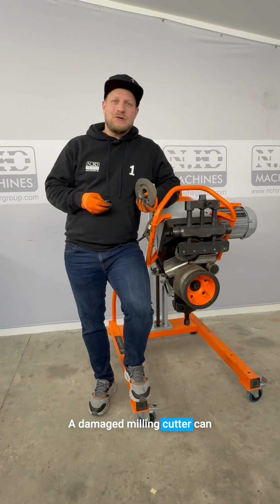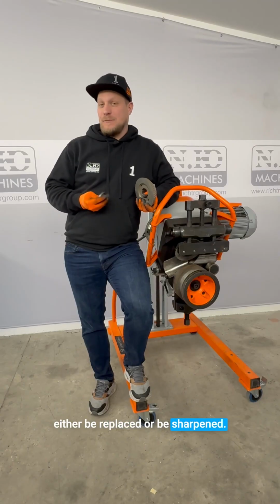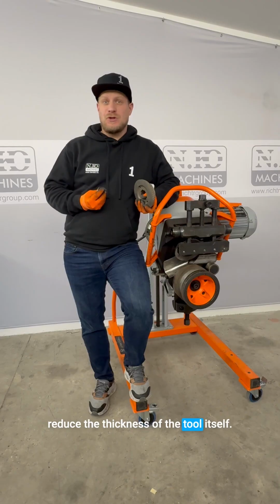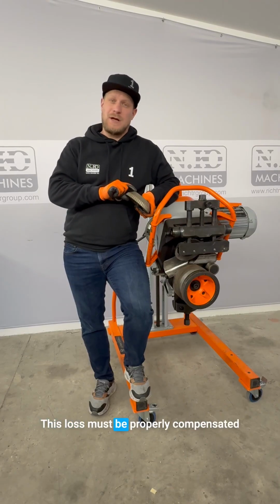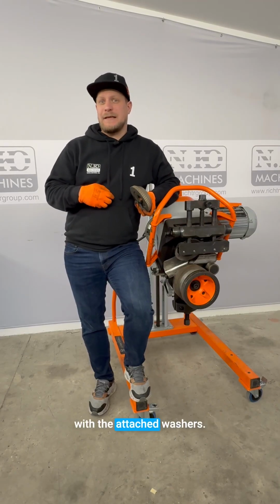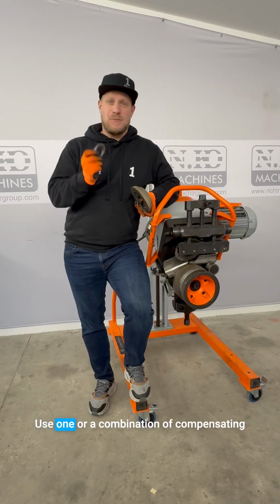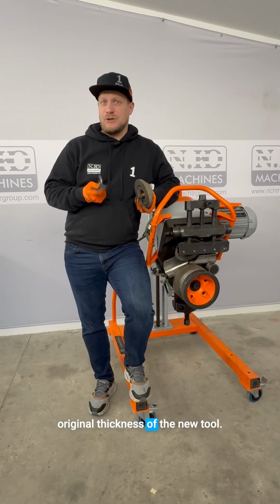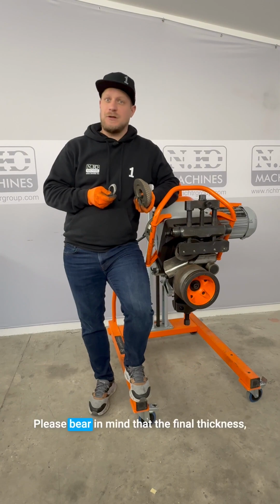A damaged milling cutter can either be replaced or be sharpened. Note that when sharpening, we reduce the thickness of the tool itself. This loss must be properly compensated with the attached washers. Use one or a combination of compensating washers to carefully achieve the original thickness of the new tool. Please bear in mind that the final thickness, including the washers, must not exceed the original thickness of the new tool.